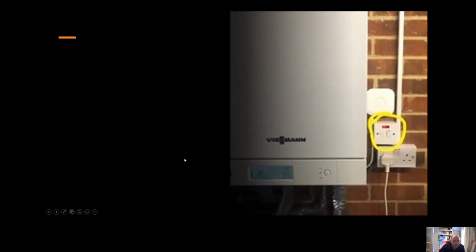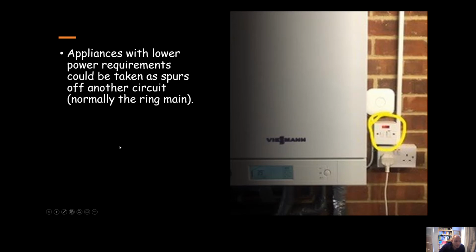Okay. Bit of key information: appliances that have got lower power requirements, for example gas boilers, because they only really need very low electrical power consumption, just to light the boiler, to keep the lights on essentially, you can take that as a spur off of the ring main.